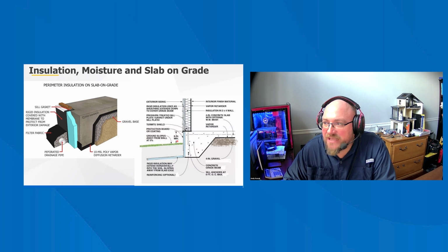The elevation of a slab-on-grade foundation should be a minimum of 8 inches above the exterior finished grade. In areas with heavy rainfall, a clearance of greater than 8 inches or some other rain control measures may be installed, such as back vented cladding and ice and water shield 18 inches up the wall. With a properly mounted slab and functional site grading, surface water should drain away and minimize the moisture load around and beneath the slab.